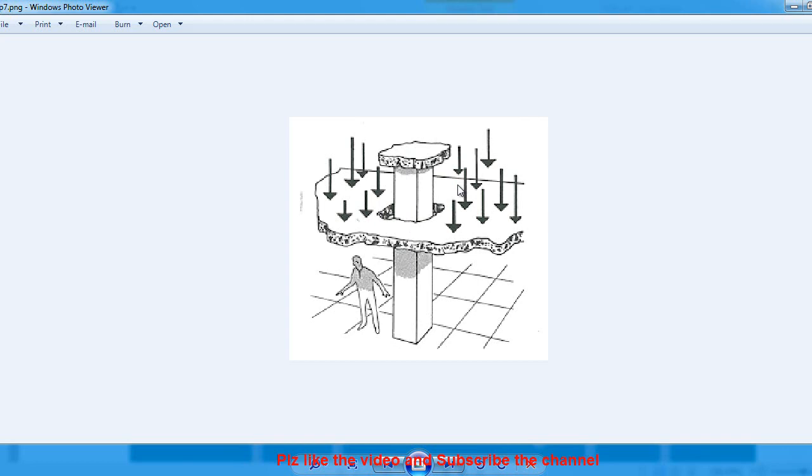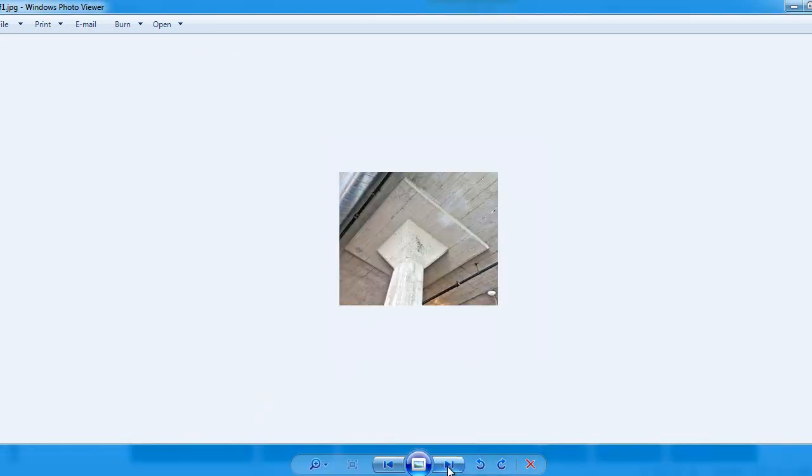Remember, this kind of failure is dominant in the lower stories of your building, where car parking is allowed. When there are 2 to 3 cars parked in the basement of your structure, due to that heavy concentrated live load, this kind of failure is very dominant, and you have to provide some kind of arrangement to control it. So you see column drop panels are provided, column capitals are provided. There is no column capital in the upper stories, because there is not such a great amount of punching shear there.